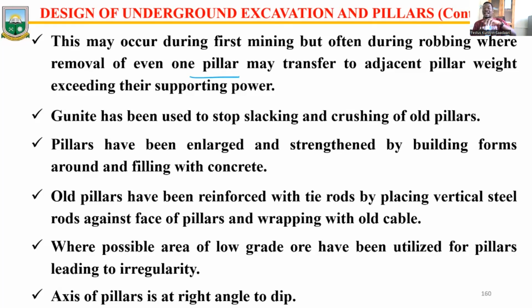So I left a pillar this size for support. Then later, after I have finished my activities, I feel like there's so much left there. So I decide that let me rob, that is robbing, stealing part of the pillar for production. And then I leave something like this. But what the note is telling us is that when we do that, we should remember that when we collapse any pillar, the pressure that was carried or borne by this pillar is going to be distributed across to nearby pillars.